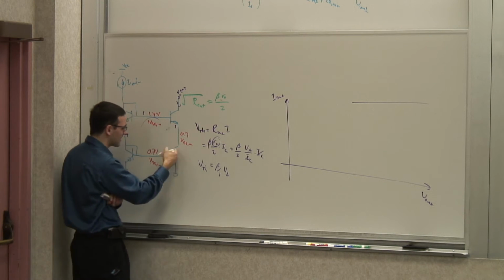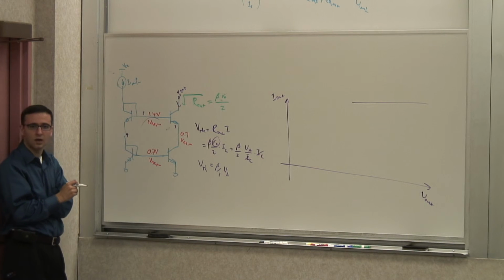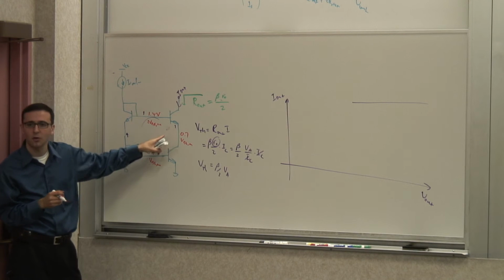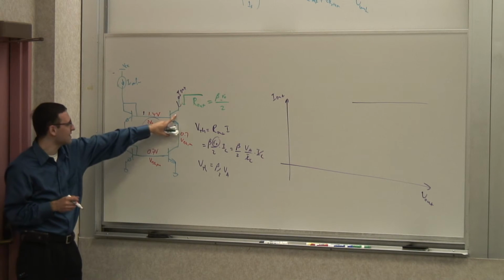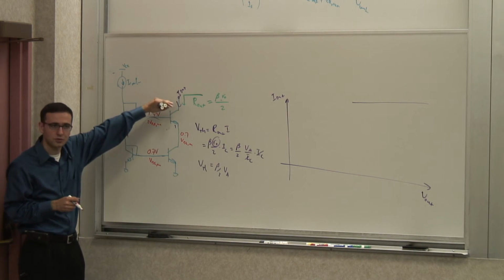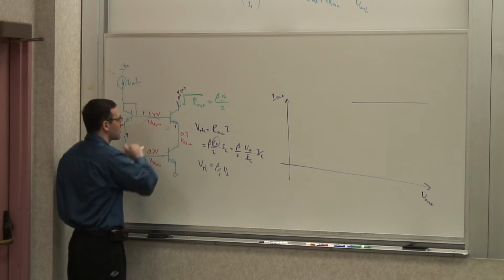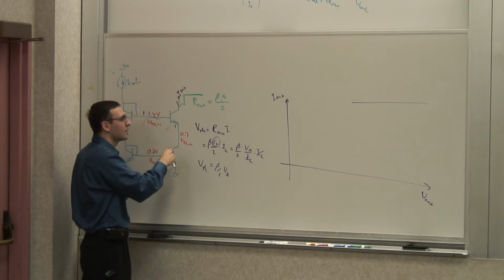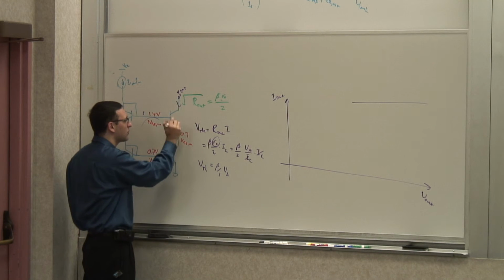So would this transistor saturate normally? No, because it's more or less like this guy. These two have the same voltage. So it's this guy that saturates first, as I lower the voltage. As I lower the voltage, at some point this guy starts saturating. Where is that point? What is that minimum voltage? Exactly, 0.8, 0.9. It's VBE on plus VCE sat.